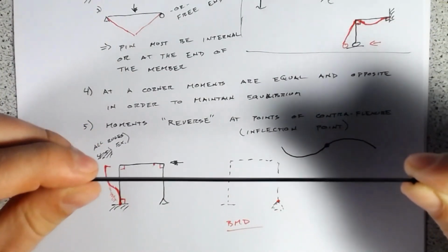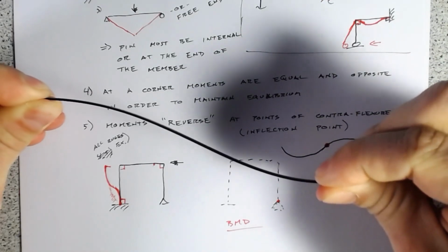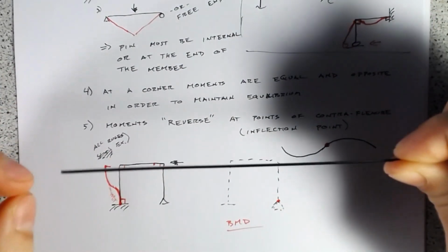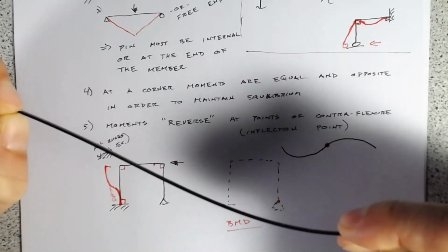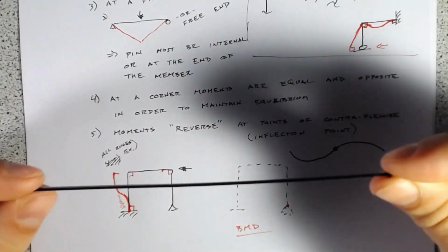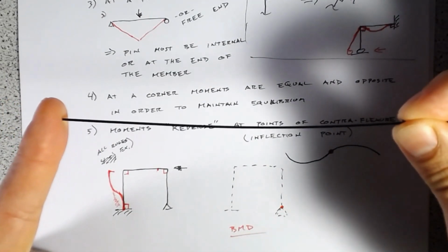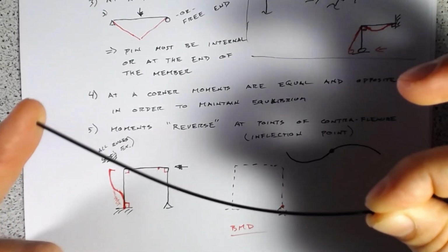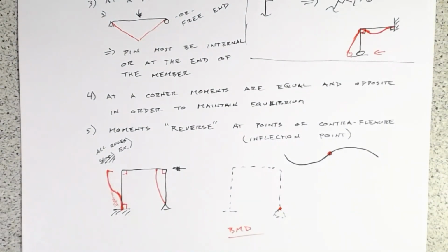So, if I have this little stick here, I'll hold my left hand still and I'll just move this. So you see, I've got a fixed end. Look, it's putting in that little S shape. Let's see if I can do this as a little pin, so that it can rotate in my left hand, and fixed. There you go. We'll pin it like this. So if it's pinned and then grabbed in my right hand, you see it just has a single curvature. It just bends in this loopy shape. So we can expect it to bend like that. So, that's what our columns look like.